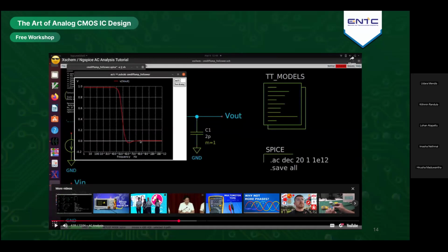To wrap up, the SG13G2 PDK really lowers the barrier to entry for analog and RF IC designs. You get full access to simulation models, layouts, cells, schematic symbols, and built-in test benches, already set up to go with XSchem and NGSpice with Magic. If you are just starting, I recommend heading over to the GitHub repo, cloning the PDK, and opening the circuits in the SG13G2 test folder. You can pick the parameters and simulate different MOSFET conditions in just a minute. You can try that.